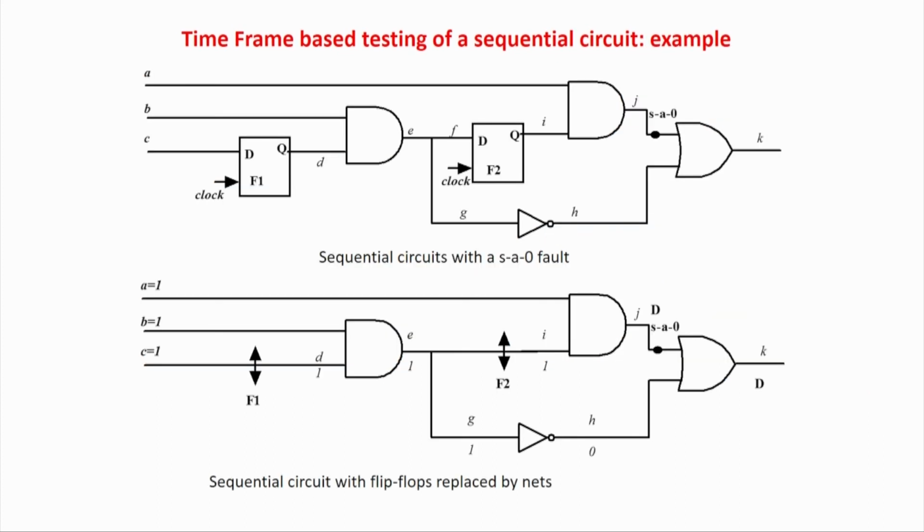For example, if the circuit has some flip flops with 20,000, 30,000, 40,000 levels, then what will you do? You have to keep on pumping the values, and it will take some 10,000 or 20,000 time units, because there is some flip flop at the level of 10,000. That means 10,000 primary patterns have to be applied at 10,000 different clock pulses. First it will set flip flop level 1, level 2, level 3 and keep on doing it. So, a lot of time will be required to pump in the values.